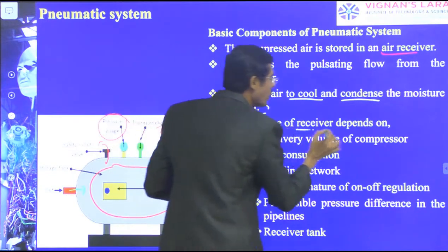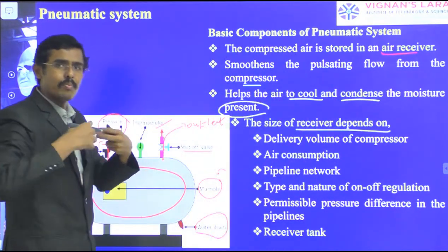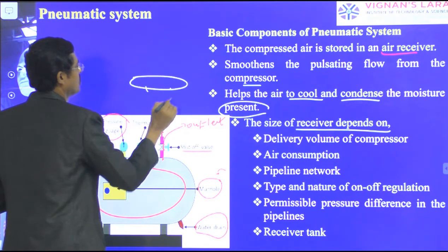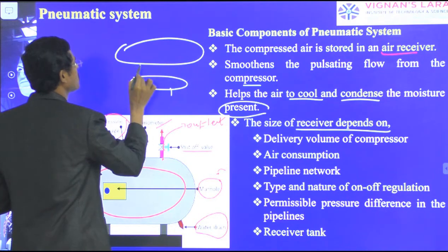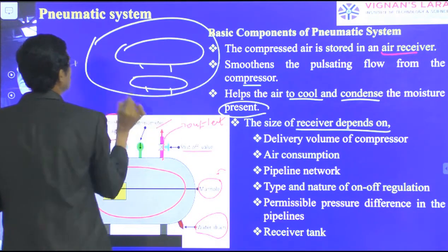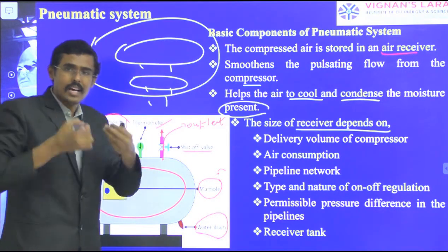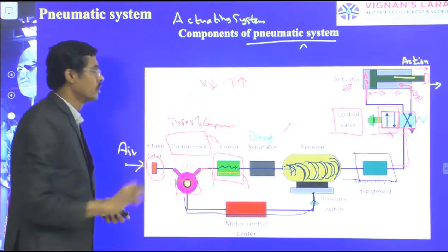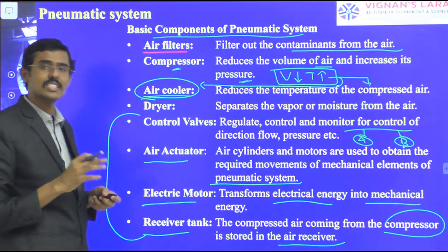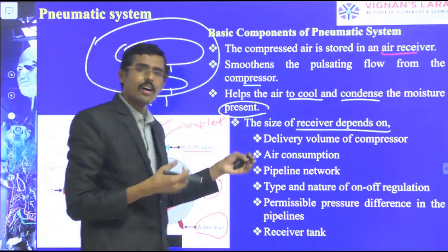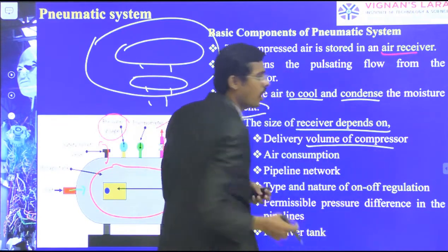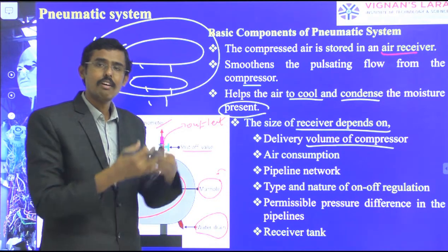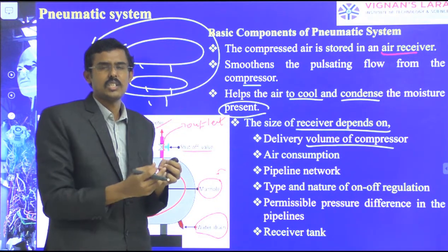The size of the reservoir depends on our applications. The reservoir can be this size, or this size, or this size. It depends upon our applications, where we are using it, what the intention is, and what load we have to push. Depending upon those conditions, I fix the size of the reservoir. It depends on the delivery volume of the compressor, how much delivery volume we have to store, and what the function is daily and per hour.